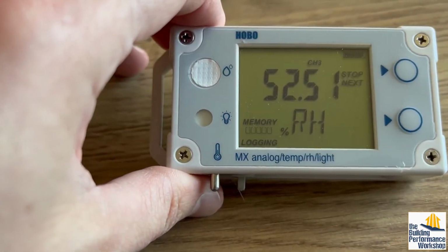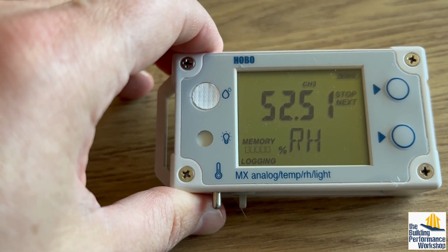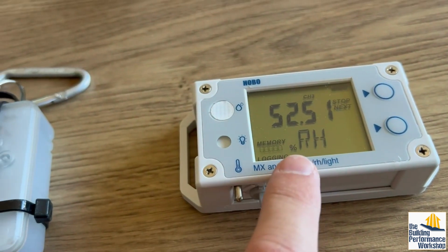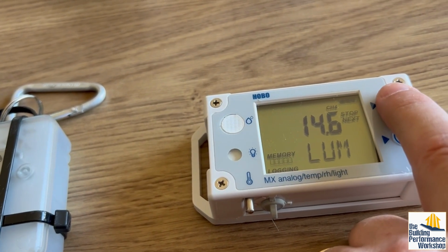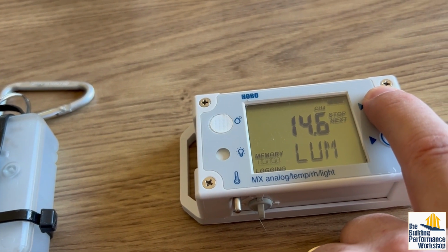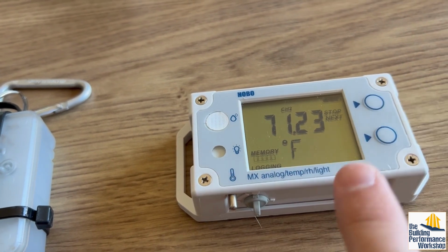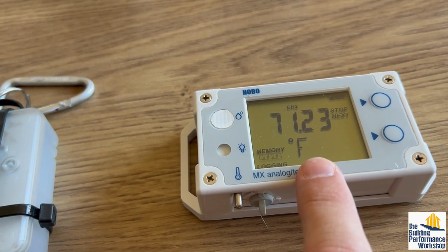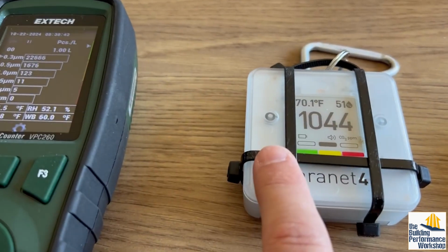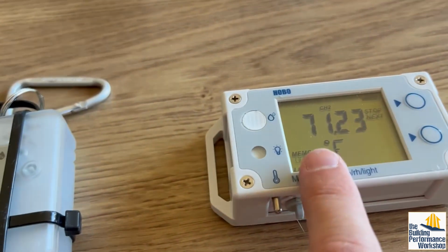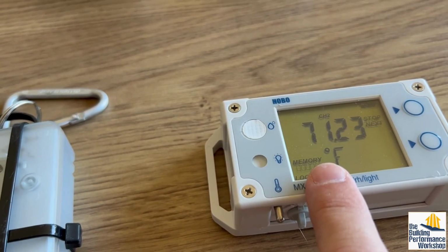We have temperature, relative humidity, and light here, and that is useful because if you want to put this someplace and then find out when the sun came up and went down or when people were in the space occupying it, you can kind of track against daylight or occupancy in a room that has no window with this kind of a thing, so that you could then take this number and be like, oh, the reason that that was here is because somebody was in the room, they were using the light.